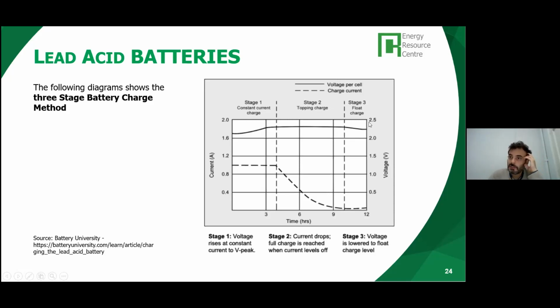So the set points, the thresholds of when the battery is at the absorption stage and when it is at the equalization stage, are defined by the manufacturer of the battery. This information has to be in the technical specifications of the battery we choose, because we will need to adjust the set points of the charge controller to operate with the voltage set points that every battery needs.